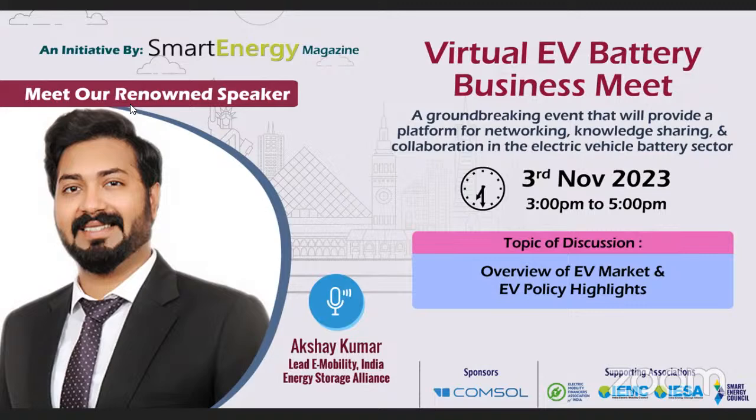Energy cells fundamentally, just now we had a presentation from Jinko. Any energy cells, so-called for energy storage, cannot be at the same energy density for the same variant when it's applied for mobility. A 100 Ah mobility cell you can achieve with 200 watt hour in LFP. You can have the roadmap and innovation on the materials to achieve 200 watt hour for mobility, because you want higher energy density in mobility. But you don't expect 10,000 cycle life for mobility.